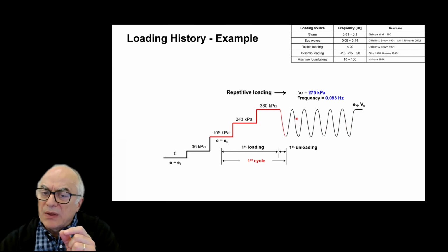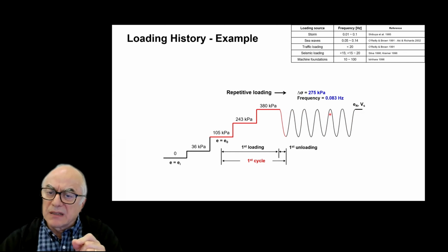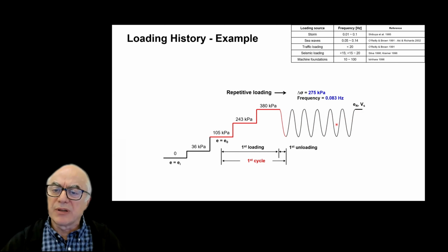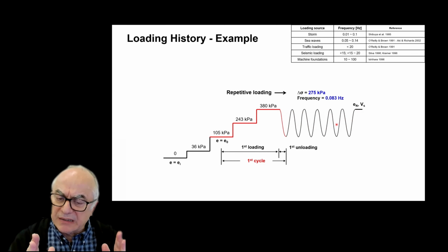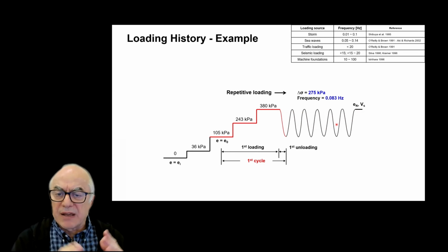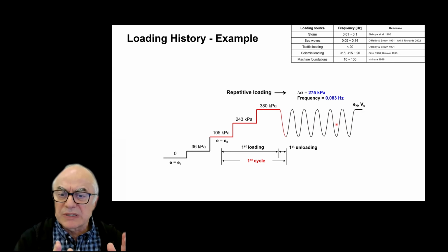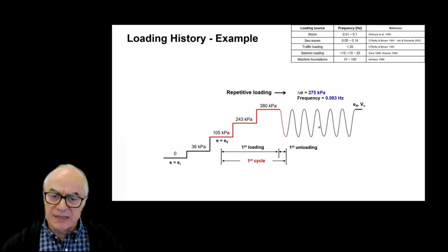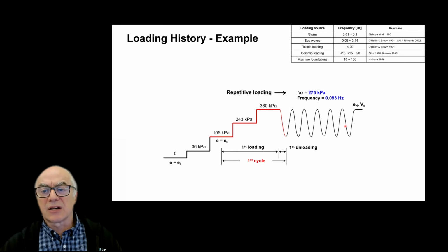And so if we wait a long time between each cycle, then the duration of the test is prohibitive. However, if we do it with very periodic cycles, let's say every 5 hertz, 5 per second, there is no time for the specimen to relax to the next condition. So we will have to optimize the frequency in order to conduct a very large number of cycles.